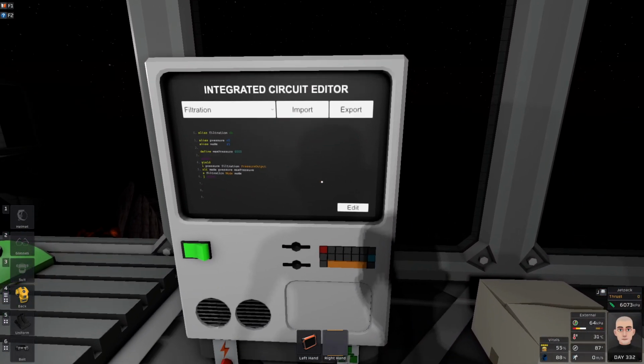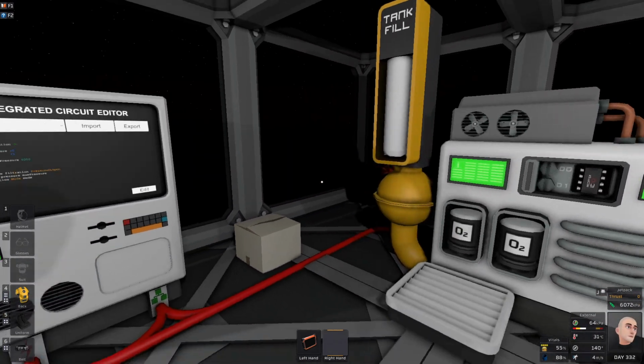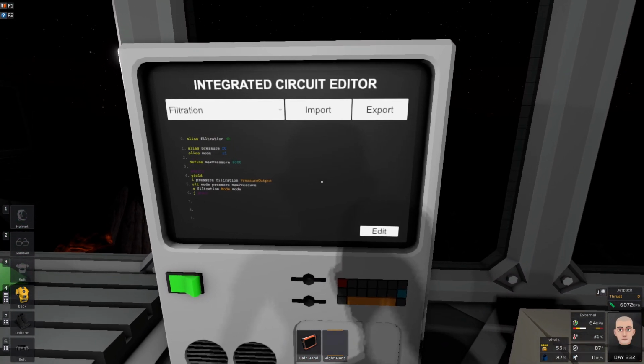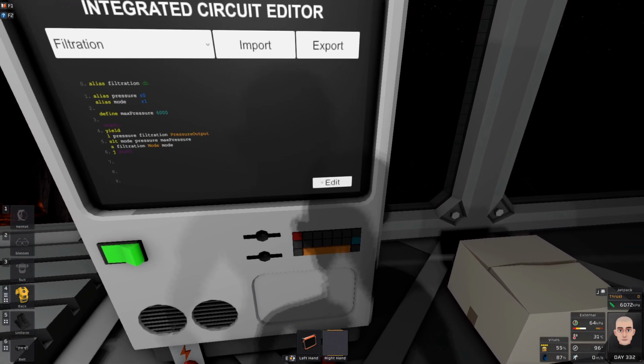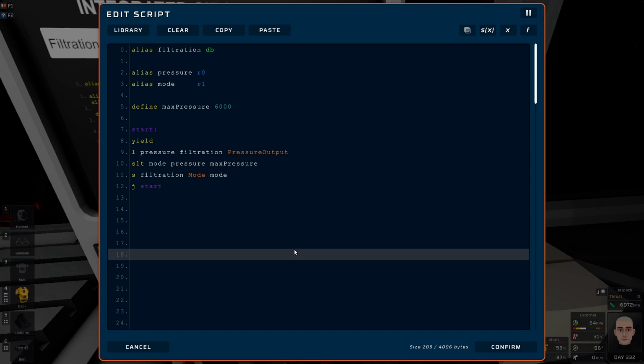In this introductory tutorial, we've seen that once we've built a contraption and operated it manually, it becomes much easier to identify the logic types required to automate the process. Understanding which devices are involved and the logic types that control them allows us to clearly formulate our program's purpose. In this case, it was simply fill a canister up to a defined pressure. Having such a clear statement about what our program will accomplish is extremely helpful when planning our approach.